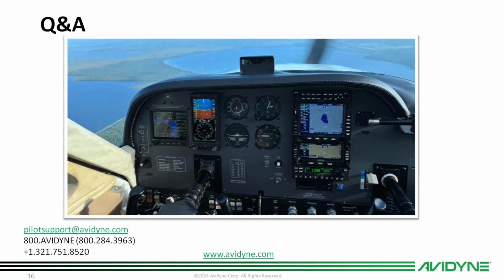Can you get weather or traffic from a Stratus ADS-B? I assume no, but had to ask. Yes, you can. If it's a Stratus 3, the IFD will accept the input for that. That's a Wi-Fi protocol problem. The Stratus 1 and the Stratus 2 won't do that. They use extended GDL90.